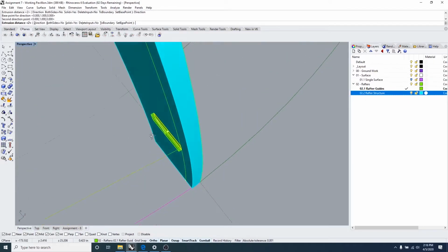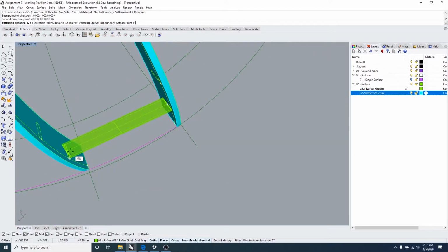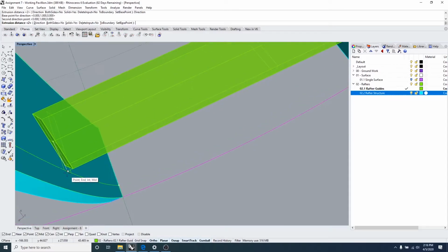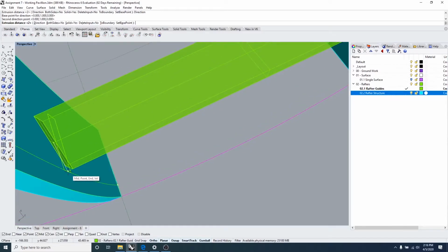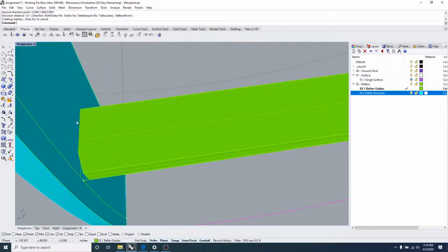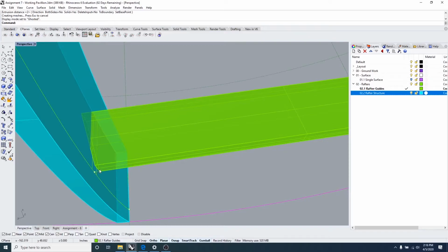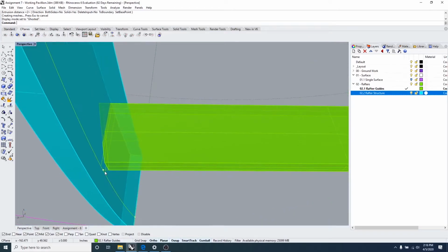It's starting to extrude from this face. Notice it's not going inside. But as soon as it gets here, if I were to finish this, notice I'm actually going to finish there. So just so that you guys can see how it's meeting in there, let me set this to ghosted. Notice that the direction is right, the profile is right, but the way that it's ending is wrong. And that's because it's ending perpendicular to this line in there.